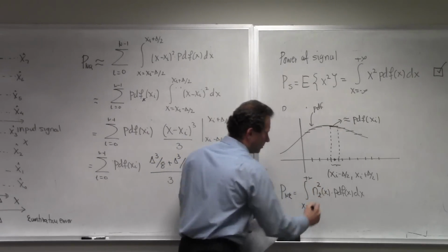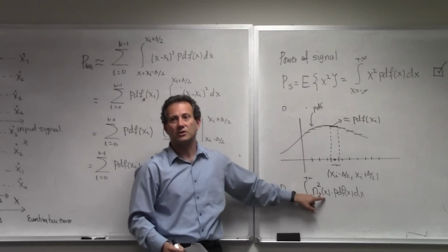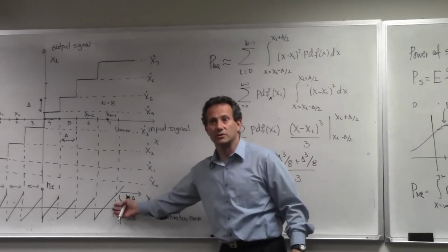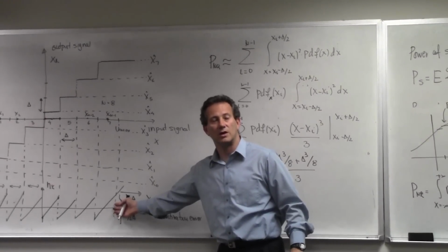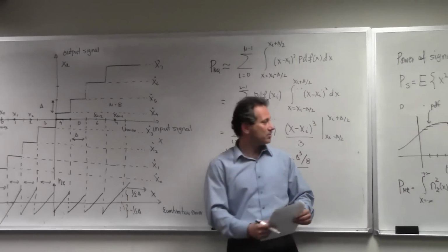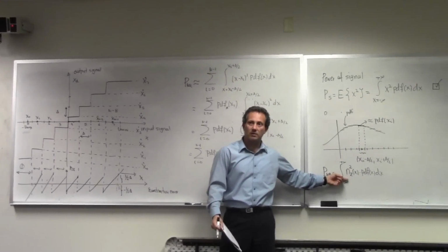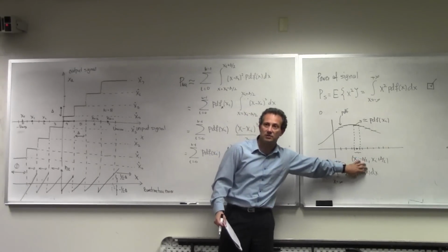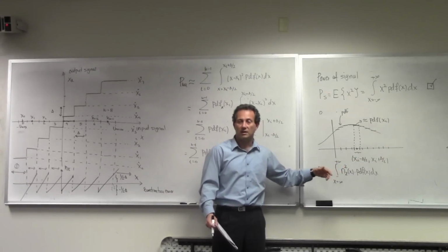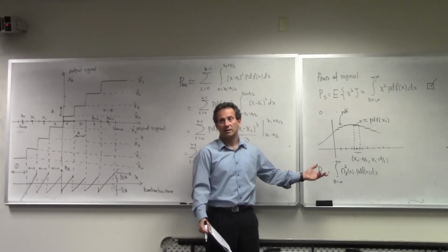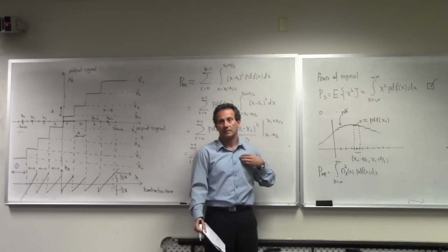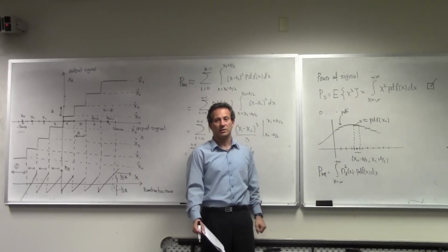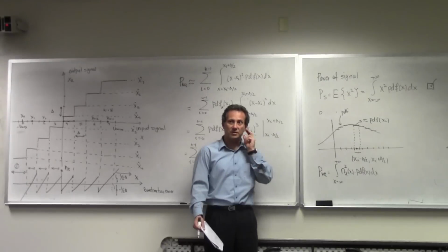So it's the expected value of a function of the input, and the quantization noise is obviously a function of the input. Give me an input value, I can tell you how large the quantization noise is. And this goes back to our review: how do you actually determine the expected value of a function? You put the function in here, attach the PDF, and then you crunch the integral. The random variable here is x. But the PDF is still of x, not of the noise. Correct, but we can, if you want, determine the PDF of the quantization noise as well.